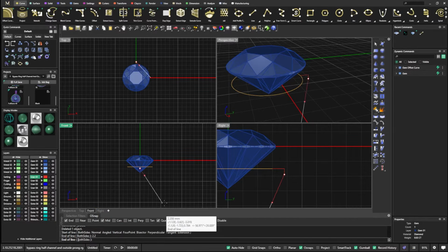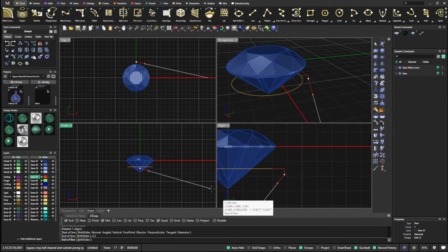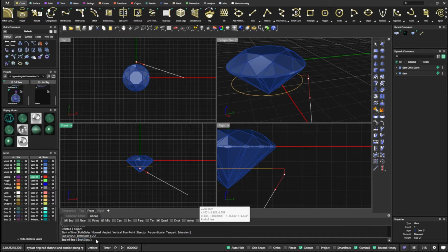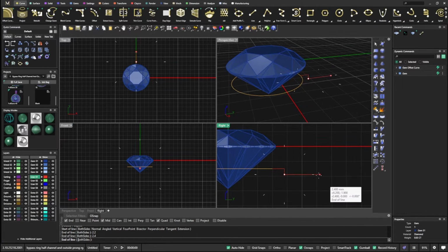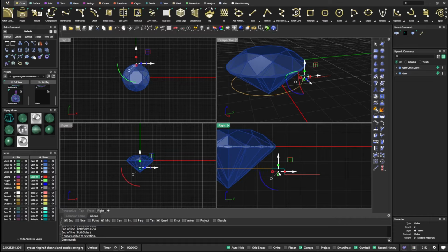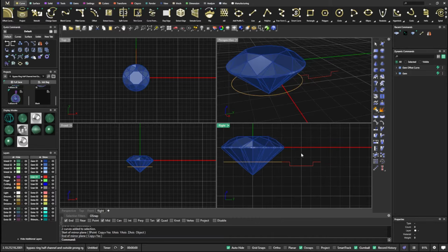2 millimeter, or probably a 2.4 is actually better. So let's come back down here. Let's do a 2.4, so we'll have a 0.2 on each side. 2.4, hold down shift, and it locks it in there. Now we can just select this because we have our mid snaps on, go to our mirror, snap to the mid there, hold down shift, and it just goes ahead and places those over there, right?